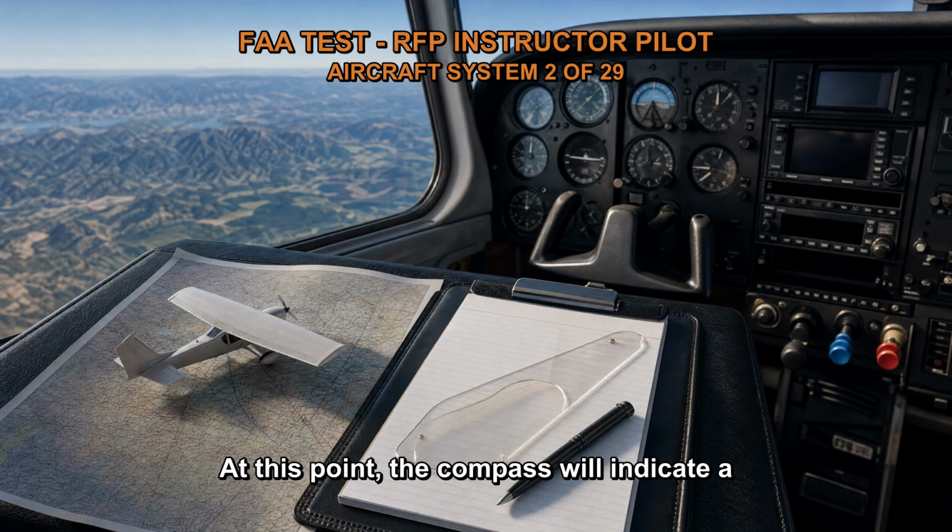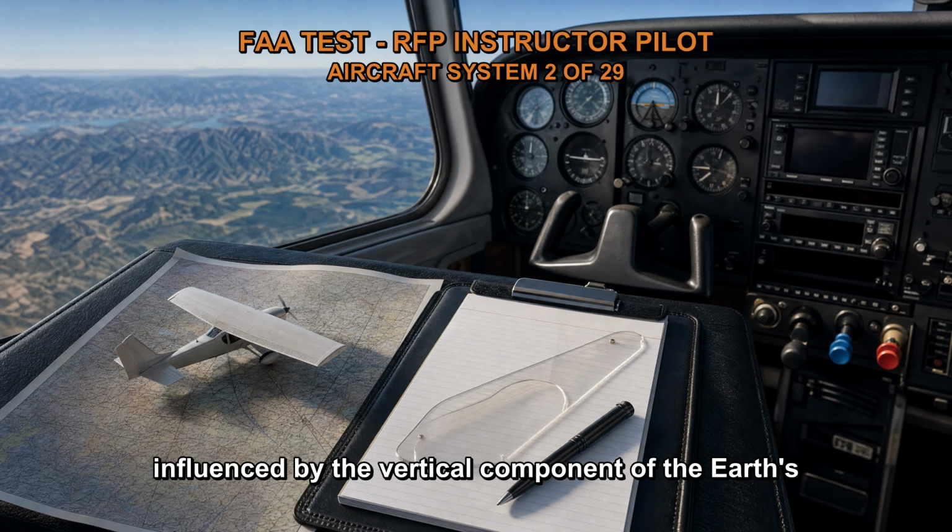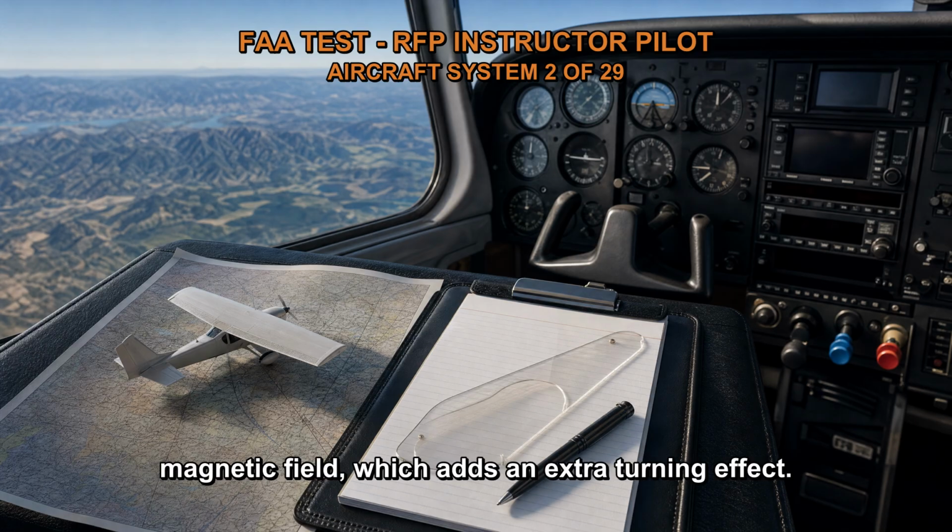At this point, the compass will indicate a turn to the right, but at a faster rate than is actually occurring. This is because the compass card is still influenced by the vertical component of the Earth's magnetic field, which adds an extra turning effect.